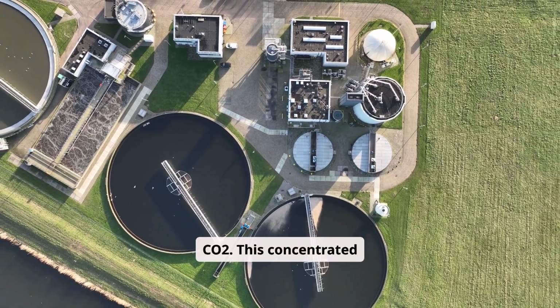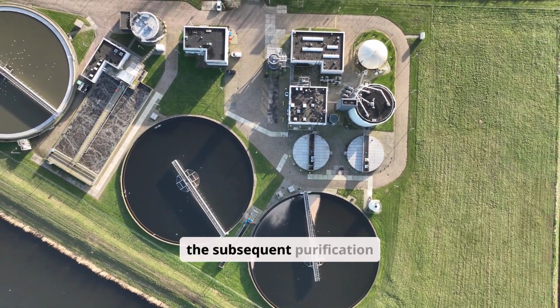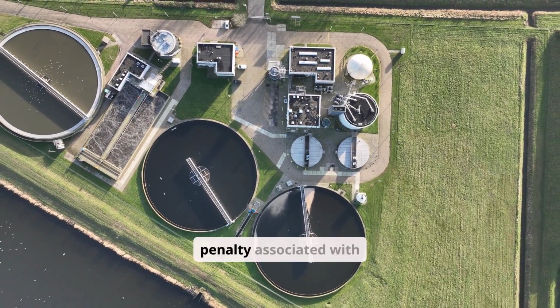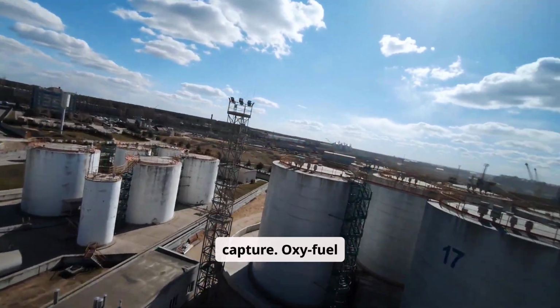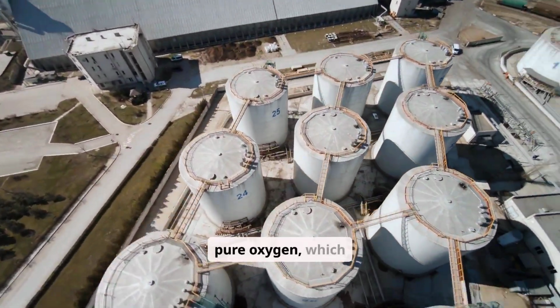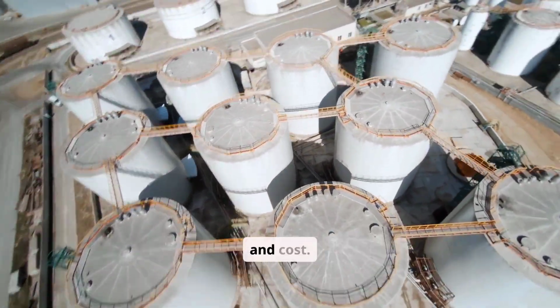This concentrated CO2 stream simplifies the subsequent purification and compression steps, potentially reducing the energy penalty associated with capture. Oxy-fuel combustion requires an air separation unit to produce the pure oxygen, which adds to the system's complexity and cost.